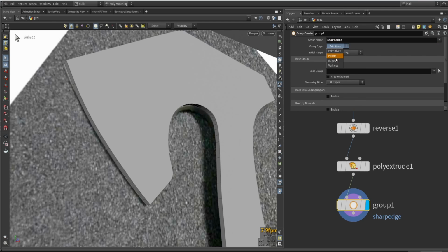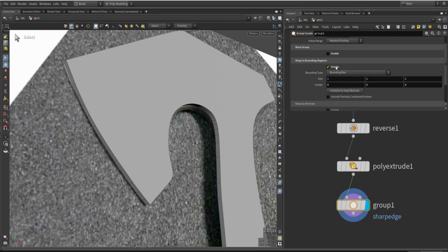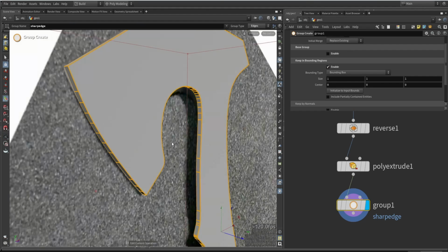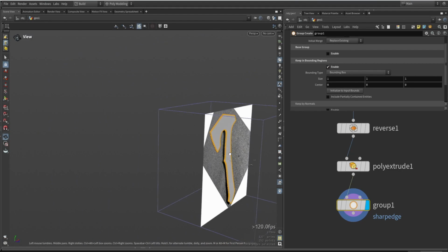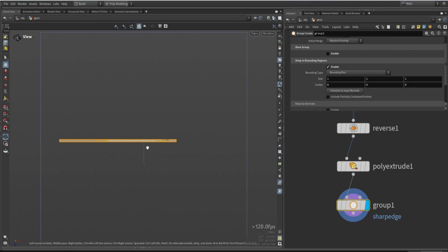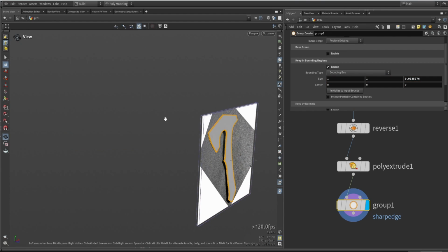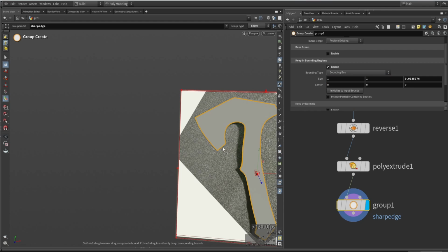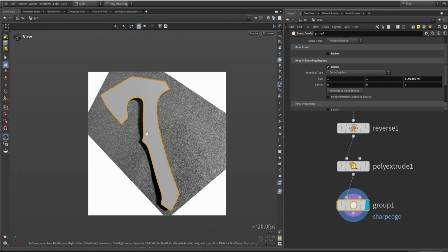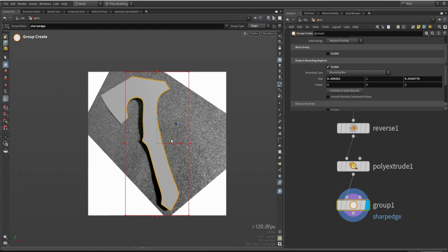This is going to be edges. This will be based on bounding box region, and we will now spawn essentially a cube here in our world. And we want this to be way smaller, so I will make it a bit smaller. We only want to cover the first part essentially, so space 3 to go in this mode.